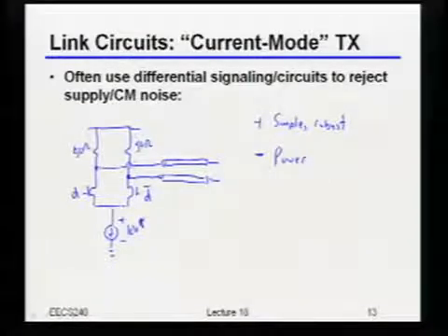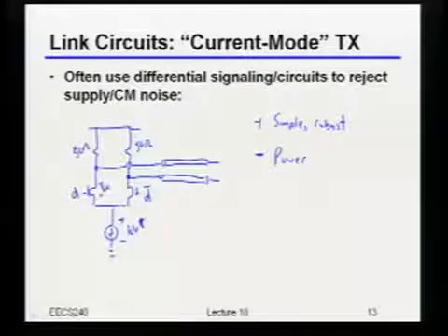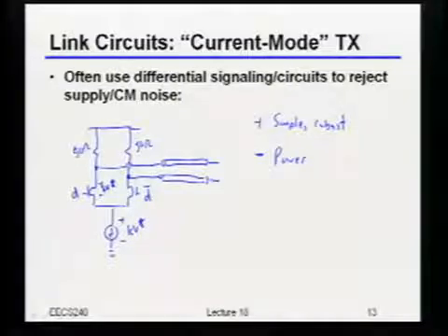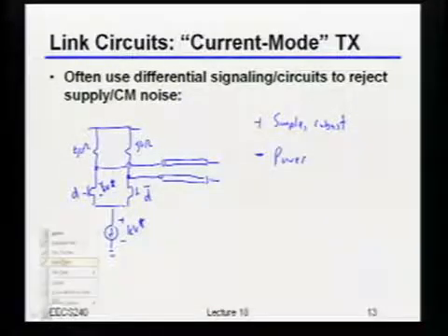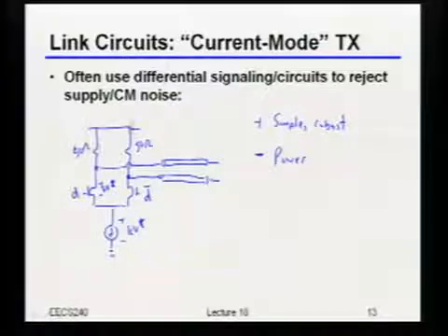And if I want this whole thing to act like a good current source, I probably want another K times V star across those switches too. That means I have to make this voltage up over here large enough that I can get the swing I want, plus still keep these switches in saturation.